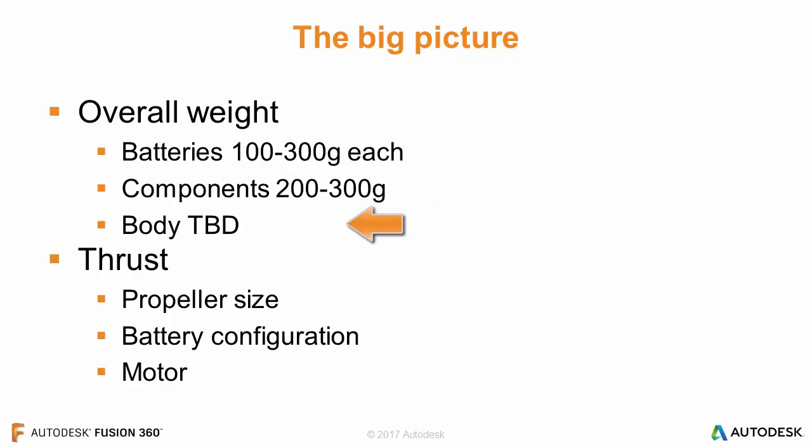Now, in general, when you're planning out a quadcopter, it's a good rule of thumb to have your battery weight be between 50 and 65% of the overall vehicle weight. Now, there's no hard and fast rule that it has to be that, but in general, when you get your batteries over about 65% of the overall vehicle weight, you're really just adding more weight to spin the motors to carry the weight of the batteries. So there's a fine line between that 50 and 65% where you're not really adding anything additional to the flight of the vehicle, in this case our quadcopter.